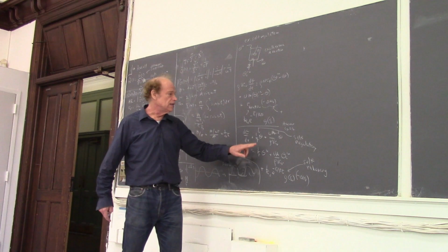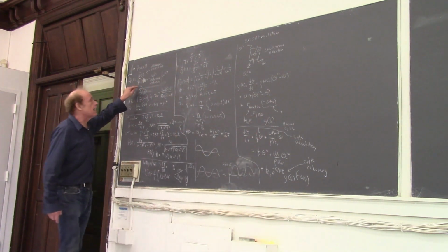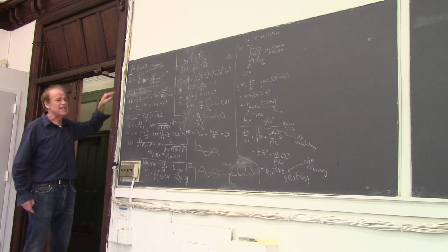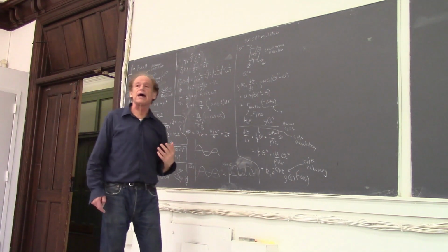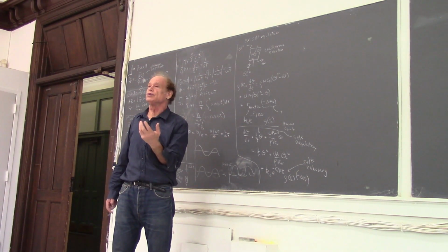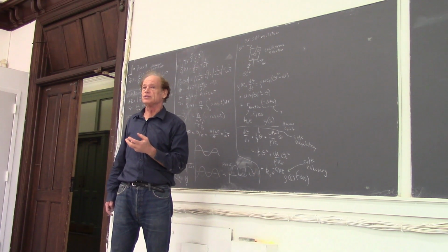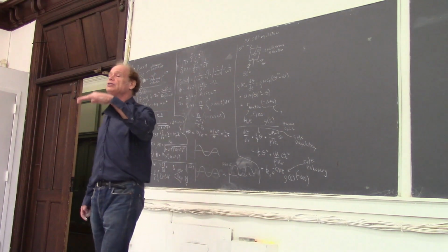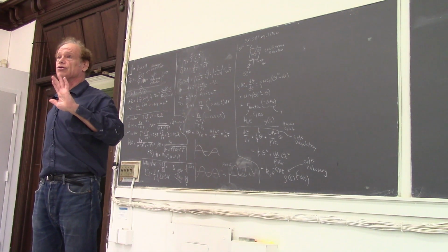So that's going to change what enters the denominator of f tilde of s, and it changes its roots in such a way that it's possible to get complex roots instead of real roots. So you can have a step change in the input that gives you oscillatory behavior in the output. That is certainly allowed.